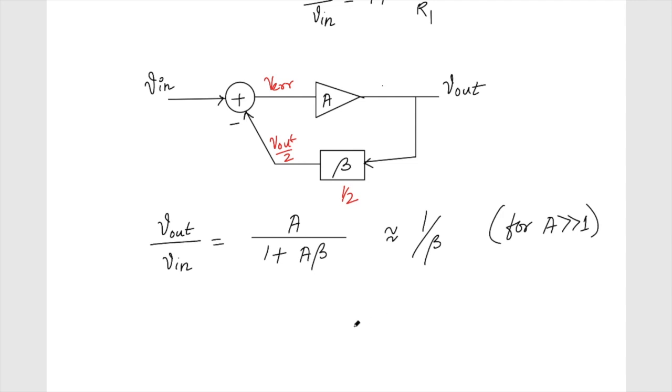This is the basic principle that we are going to use in a PLL design. If I want the output to be n times higher than the input frequency, that means I'm supposed to divide that frequency by n and compare it with the input, and make sure that the divided output and the input are almost the same.